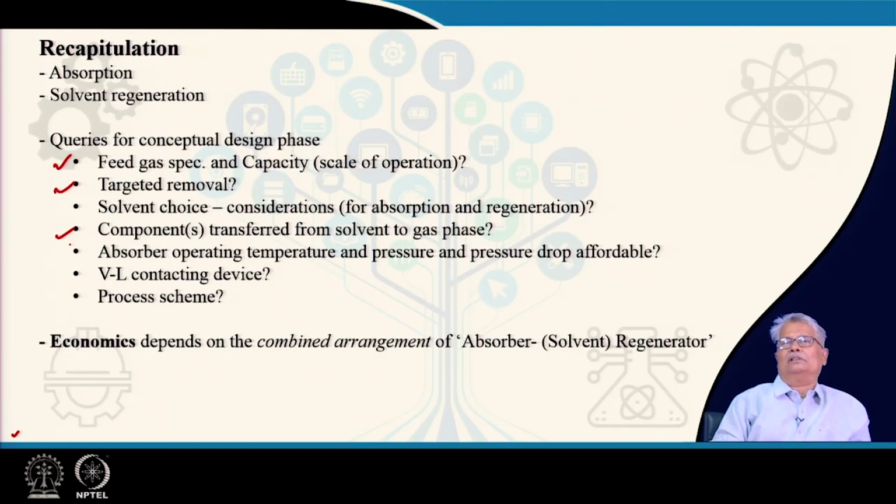And if we are talking about the pressure, we have to talk about the pressure drop in the equipment, and definitely the supply pressure of your gas should be sufficient, so that the affordable pressure drop can be availed from the source. If it is not possible, then definitely the pressure has to be boosted by either a blower or a compressor, as the case can be.